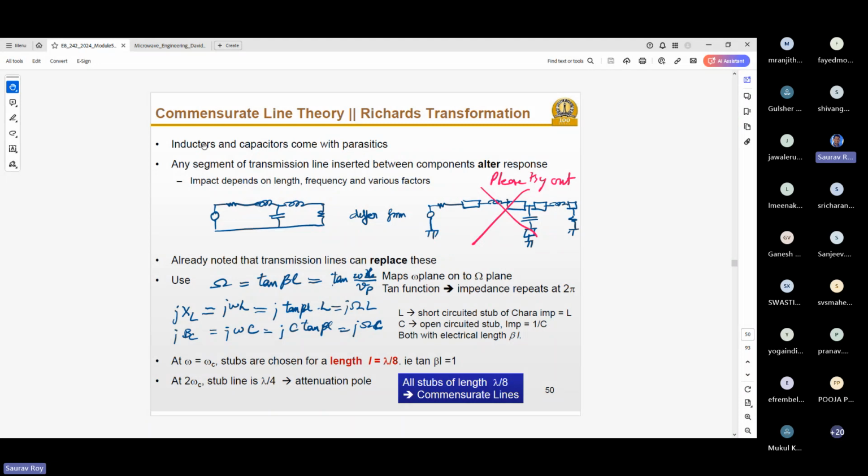And not only that, if you see in this picture, let's say this is a low pass filter we have to replace; we have to design the same thing on a substrate. So now on the substrate, you cannot directly connect it. You need two pads, right? Two pads to connect L and C. Let's say you use lumped elements only, you don't go to anything else. But how do you connect them? You need multiple pads to connect to your circuit on your substrate. Now, the moment you add these pads, they will lead to some extra additional impedances. So that will definitely change your line characteristics.